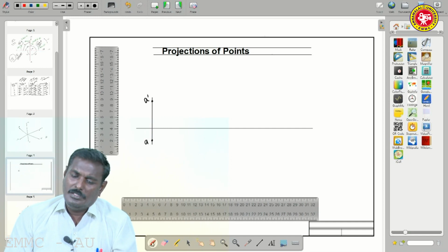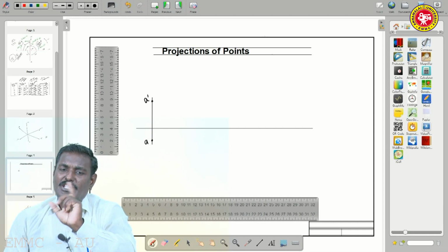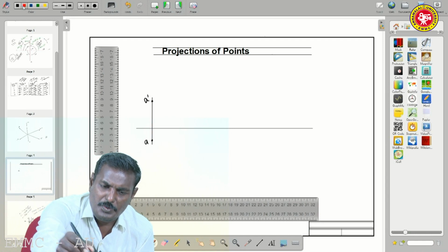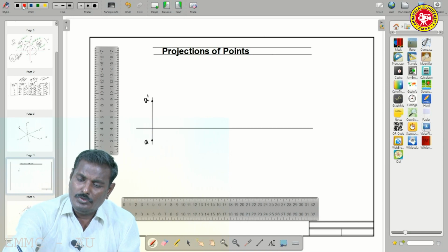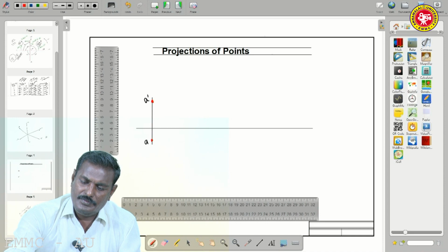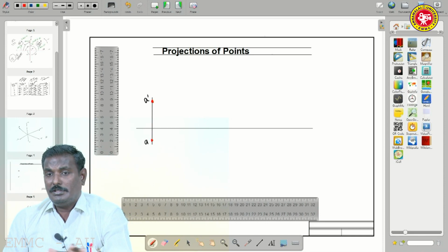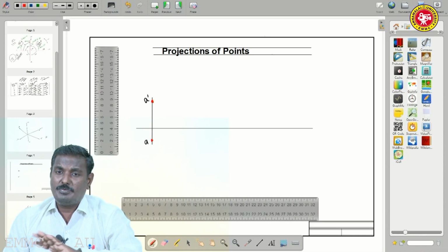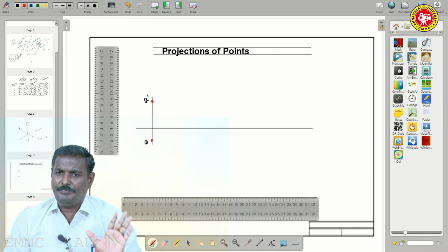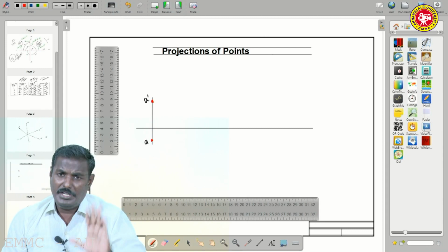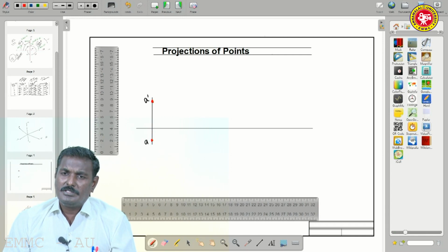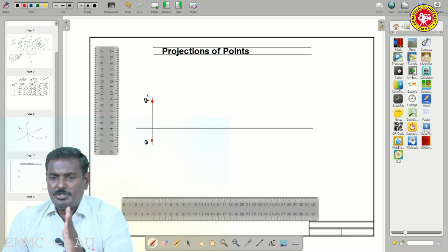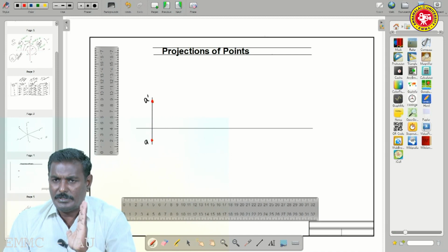Now take the H pencil. I am using the H pencil as the red color. You have to represent dark points, it's very important. Whatever is black here should be 2H pencil. Lettering is HB, mine is lettering HB. So red color represents the H pencil. So subdivision 1 is over.